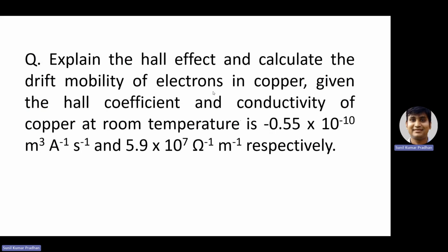Hall effect is applicable to metals as well as semiconductors. It says that when a metal or semiconductor, that means a current carrying conductor, is placed in a transverse magnetic field, that means your magnetic field is perpendicular to the direction of your current, then an electric field is generated perpendicular to both current and magnetic field. That is the explanation of Hall effect.